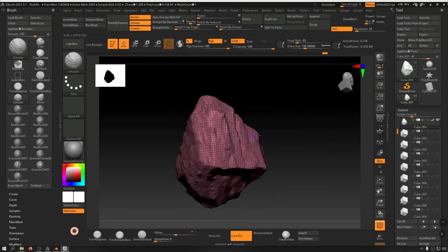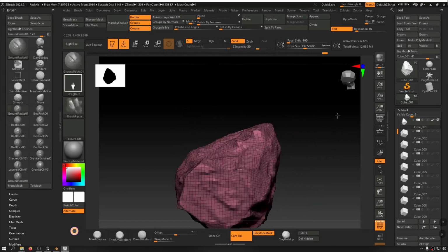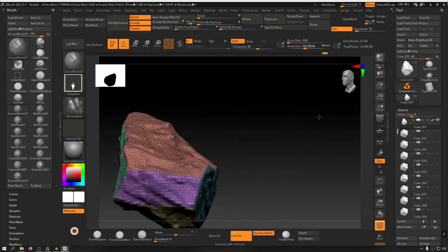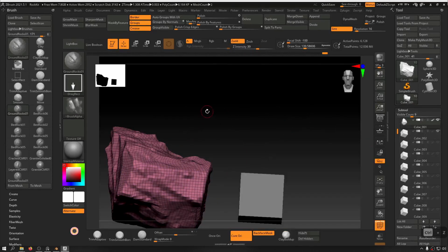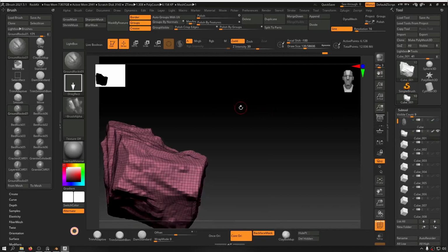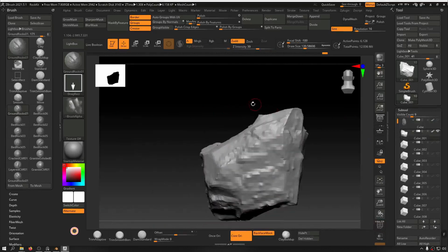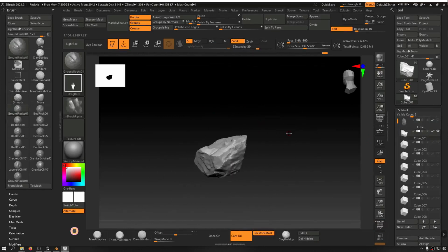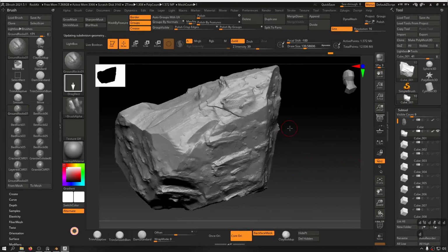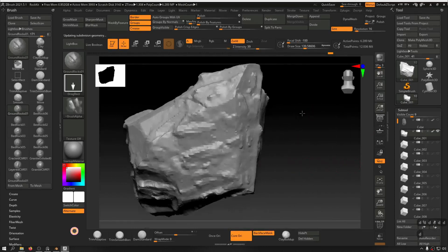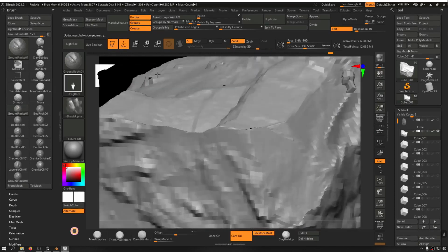Okay, and I believe it has done it. So let's look at the UVs. Auto group with UV. Okay, we got perfect UVs here, and we can simply go to the next one because this has been UV'd already. So let's turn it back, go a couple of steps up by hitting D and watching everything that we have created. Okay, it's perfectly there and UV'd as well.